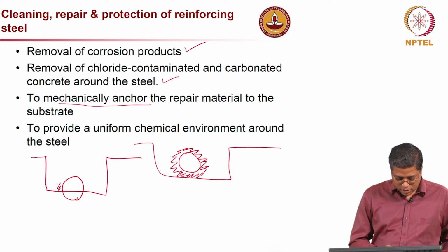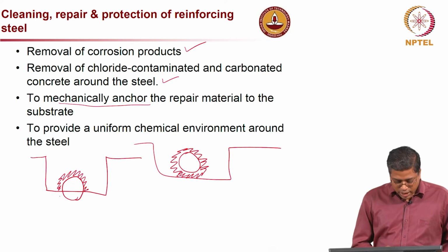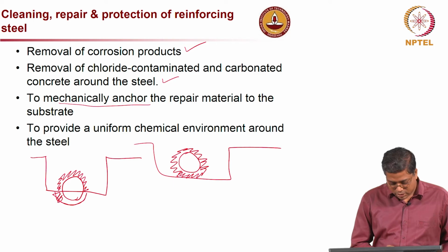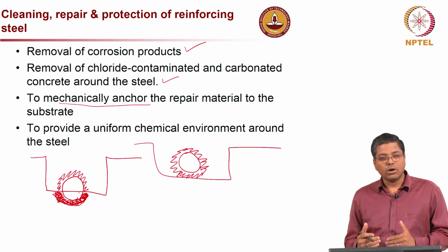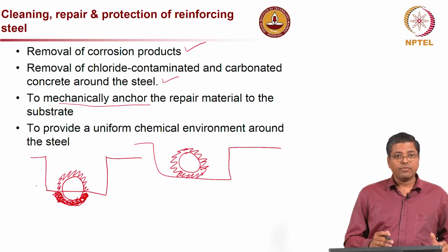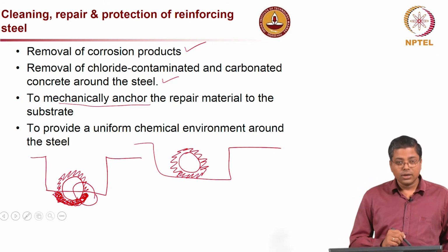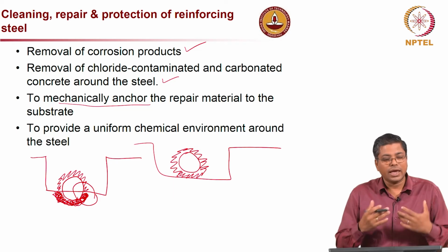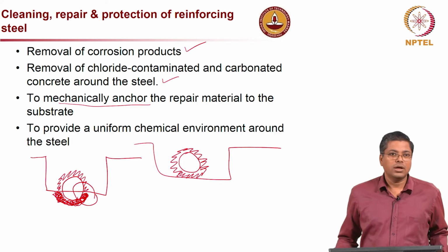In such a case, the new repair material will be only up to here. And this portion at the bottom of the bar, this darker shaded portion, will be the old concrete, and the top half will be new concrete, and that will create a battery like here. So, what it means is there is again a possibility of corrosion happening in the very near future.